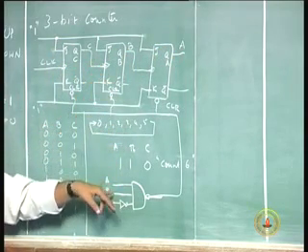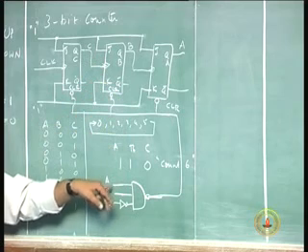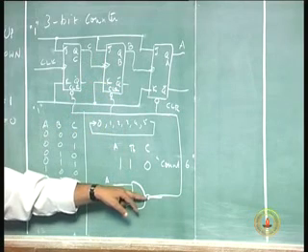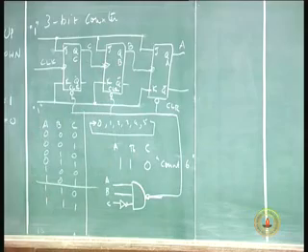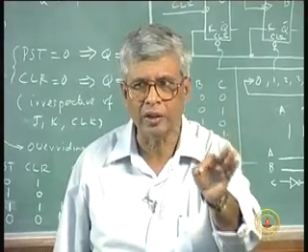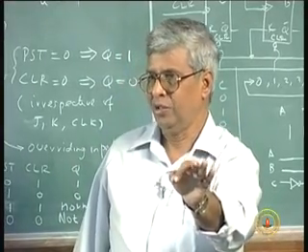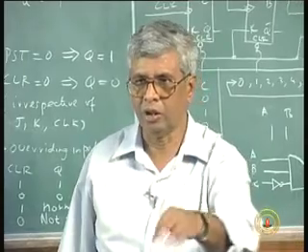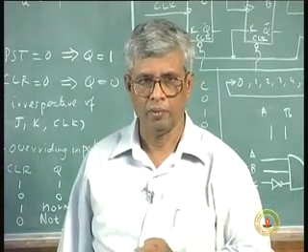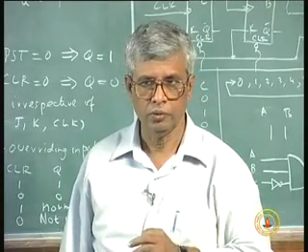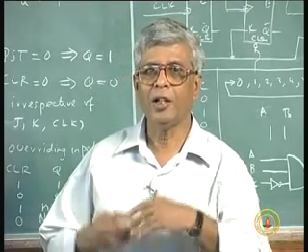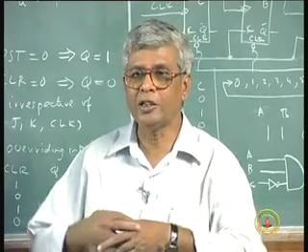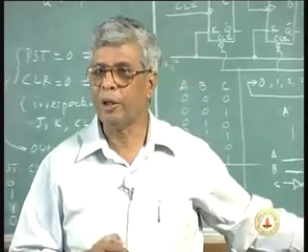So as soon as the flip-flops A, B, C take the value 110, this becomes 0. So I would have a count 0, 1, 2, 3, 4, 5, and a momentary short duration count 6, which can be ignored as a glitch, and then start all over again at 0. So I can use this to do anything now. I can start at any point. If you want to start not at 0, I connect it appropriately to preset and clear.